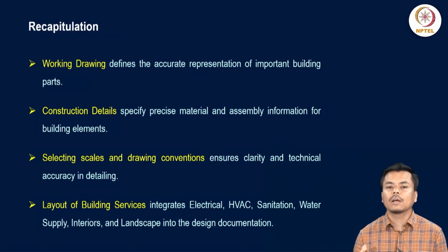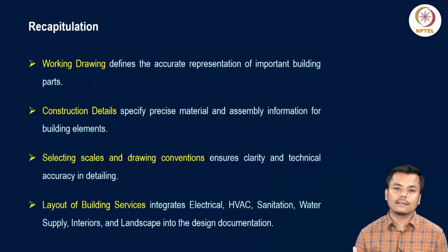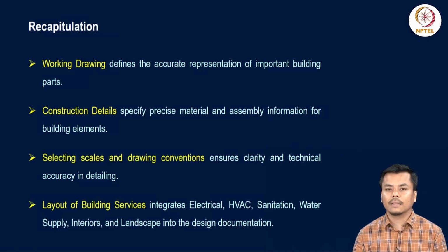So the tile layout, the presence of any loft or any internal overhead spaces, all these are to be represented in the working drawing, along with the proper dimensioning of the openings and the other aspects that are there in the floor plan, such as if you have created a niche within the wall, how and where it is to be exactly located. These informations are basically shown along with the details about the tile layout. How the tiling is done within the floor is also highlighted in the set of working drawings, especially in the floor plan.